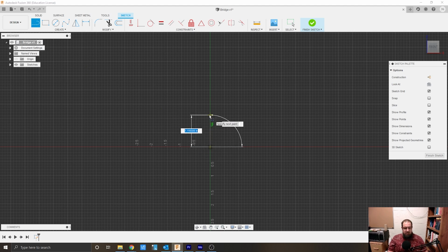Now this part of our section gets into the idea of, do you want to do add-on, or do you want to do cutaway for general design? For myself, I utilize cutaway because it's easier for me to cut a circle in there than it is for me to add an arc in there later on. So we're going to put in my height. My height is 1.5. Okay, that looks good. My width is 2.75.